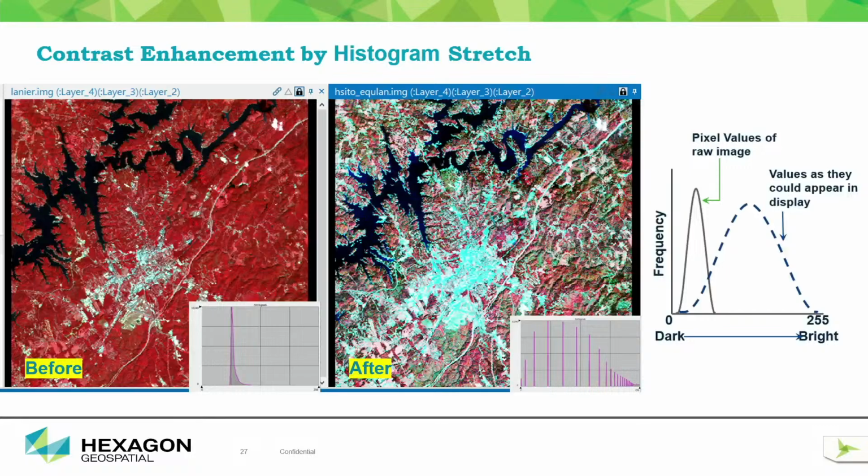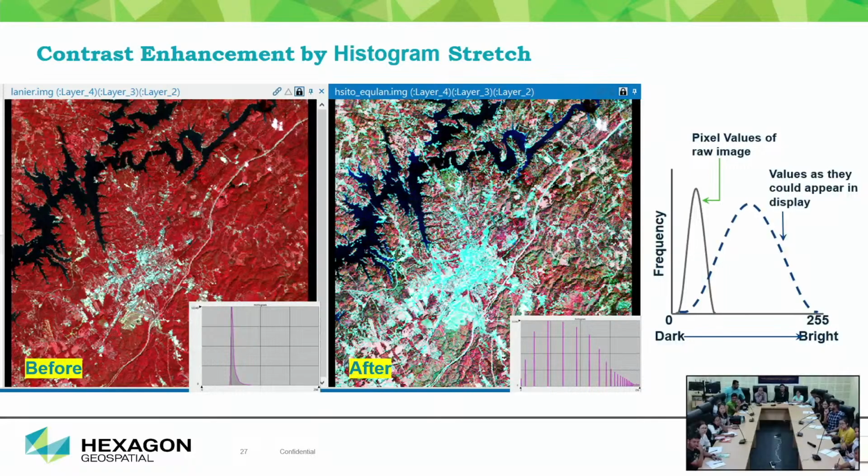So here you can see that the image's pixel values are coming in between some range, and we just stretch this range to 0 to 255 values. So the identification of the image's features, or their power, is increased by this. That is known as histogram stretching. And using the same technique we have histogram matching also.